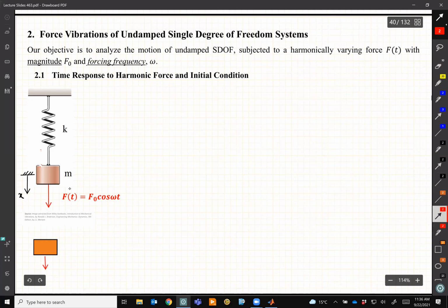So I have an external load. That external load is F(t), whatever function it is. And then I have, of course, a spring, which is kx. So I assume that the system, I disturb it by x because of now this force. So this is my free body diagram. So the Newton law simply says sum of the forces is ma, because it's a particle. We don't need to worry about the moment.